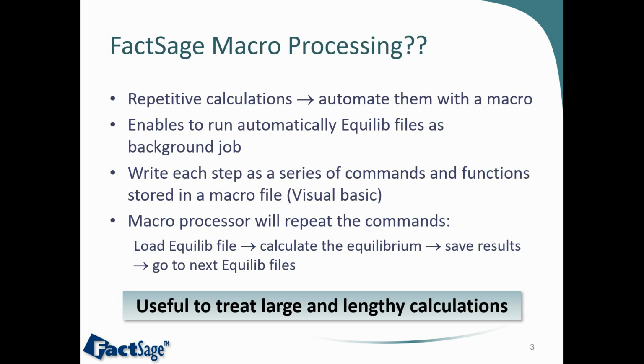So what exactly is macroprocessing? Macroprocessing is built in FactSage, so you don't need to install anything, it's already there. And it gives the users the ability to run equilibrium calculations as a background job. So whenever you have repetitive calculations, you can automate them with a macro.